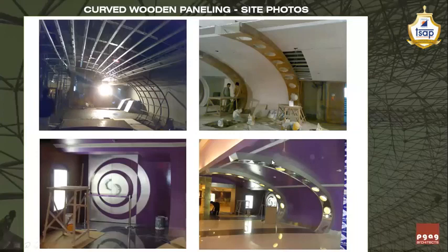We had to give grooves. After finishing the gypsum, we had to give grooves of 3 mm in this Duco paint finish, because in the Duco paint finish, if the surface is very large, it is going to get cracked. Like it happened to get cracked. To avoid those cracks in the Duco paint finish in the later stages of the execution, we have given 3 mm by 3 mm grooves in this particular paneling. You can observe that in this particular photograph.